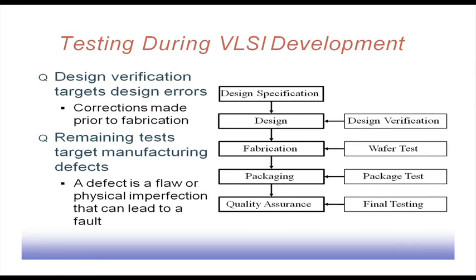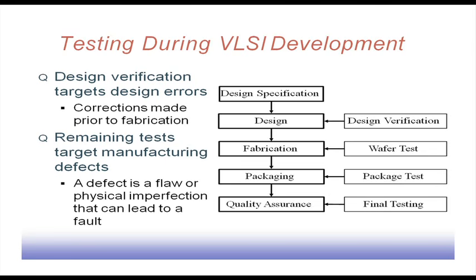But the basic problem with the wafer level test is that at that point these wafers are open. They do not have any protection, like packaging and all that. So, they cannot tolerate voltage fluctuations or very high voltage, very high power, etc. As a result, this wafer level test is very delicate, and we need to take special care while doing this. But we cannot avoid this stage, because it requires us to check the correctness of the individual devices that are fabricated.